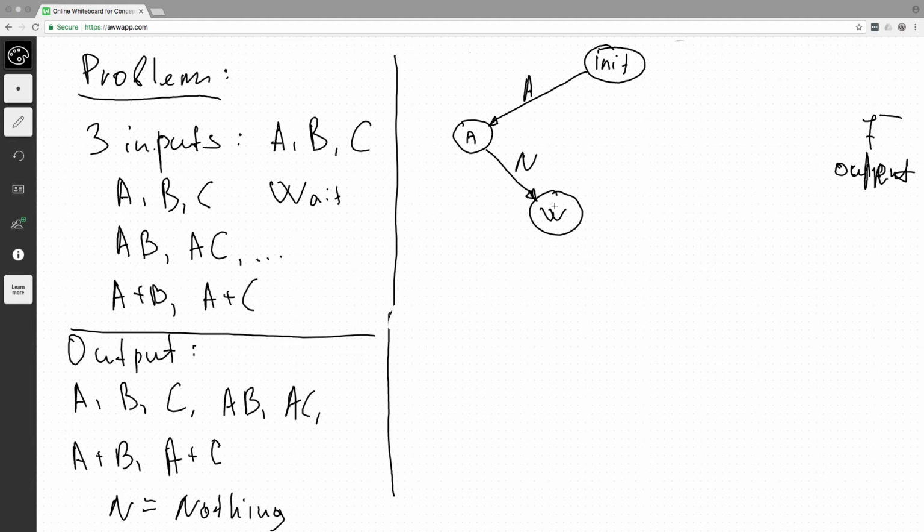In state W, we can initialize a timer or some form of delay counting mechanism. And that delay counting mechanism will tell us that before the timer expired, signal B was introduced, or signal B was not introduced and the timer got expired.